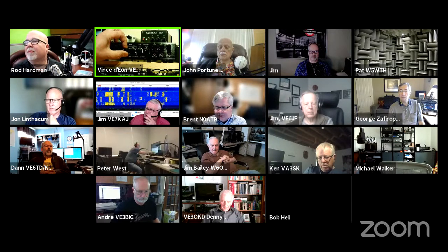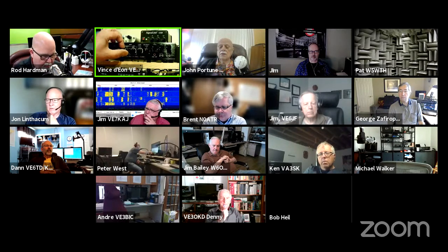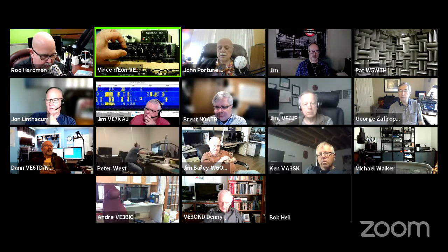I'm at about 800 hertz, waiting for him to talk. You can barely hear him, right? All of a sudden, you can almost hear the guy. I need a better signal for a demo. I need one that's probably 6 or 12 dB instead of one that's just at the noise floor. So let me go find one.